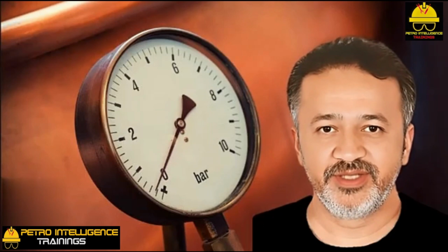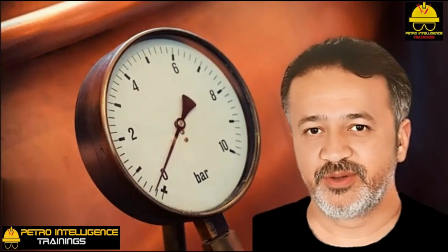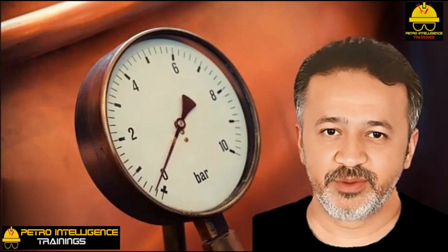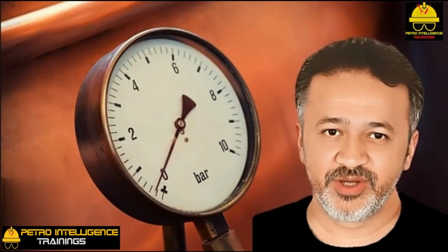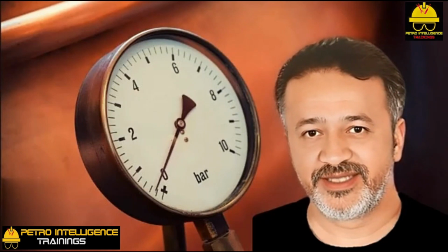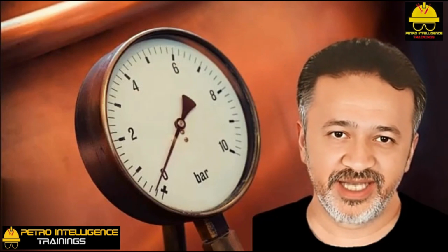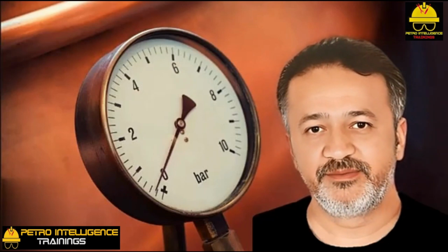About 5% of the TI points used are not located where the unit piping and instrumentation diagrams, P&IDs, show them to be. Then, pulling the thermocouple from a point in the process sometimes causes an unexpected drop to ambient temperature at an entirely unexpected TI location.